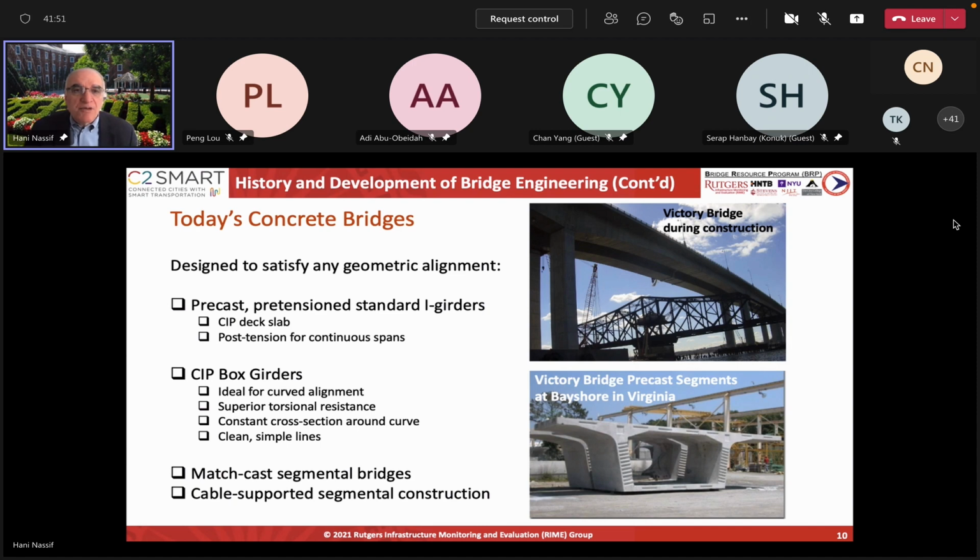So there are two types of pre-stressed concrete. There's a precast, pre-tension, and it can take different shapes. The pre-tension usually, we make them in the pre-stressing concrete plants, and it can be a composite with the decks, usually when we put them on the bridge. And there's also post-tensioning, which is mainly unbonded tendons.